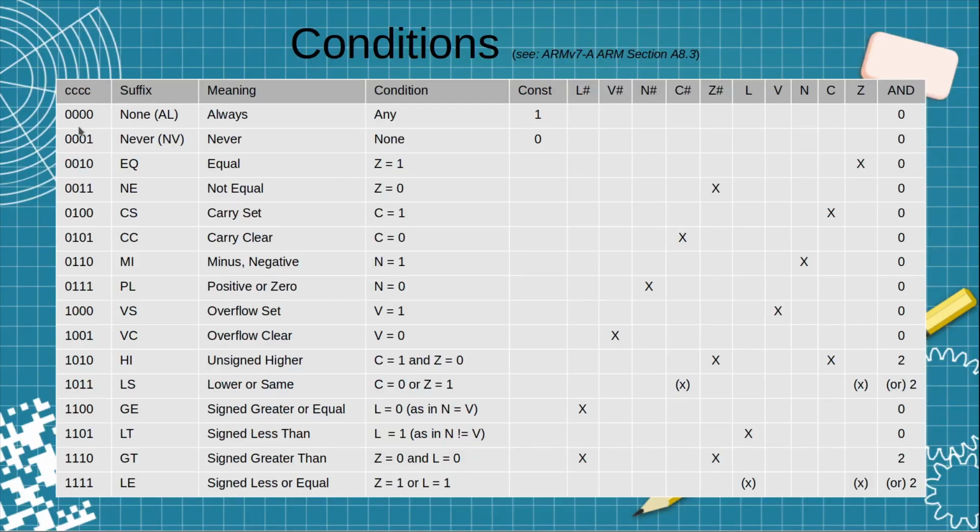And then what would end up happening is these 8 different conditions would be handled by one of the 151s, and these 8 conditions would be handled by another 151. And the original intent was to use this most significant bit here to determine which one was enabled. That would require an inversion of one of those bits, or that most significant bit, to make the determination.